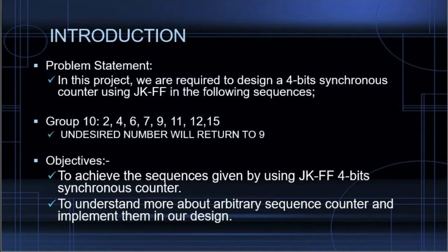JK flip-flop is basically a gated SR flip-flop with the addition of a clock input circuitry that prevents the illegal or invalid output condition that can occur when both inputs S and R are equal to logic level 1.